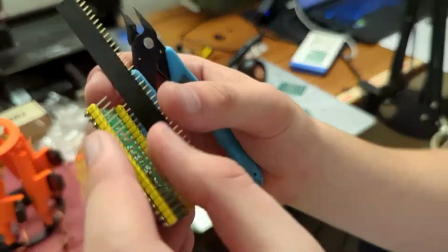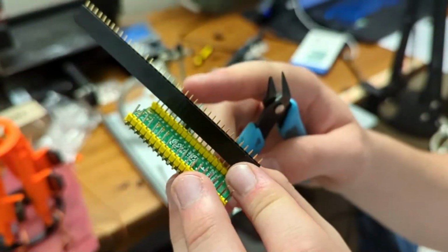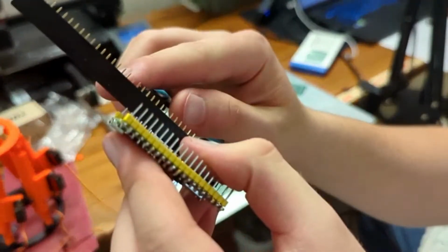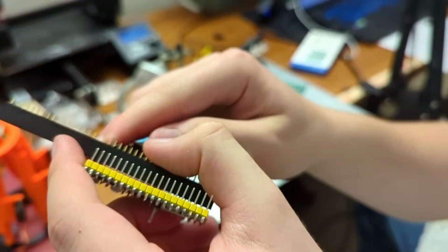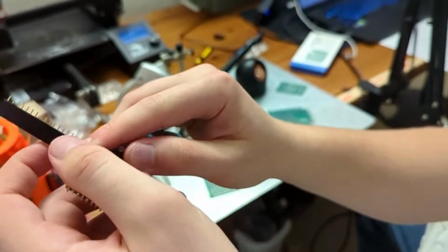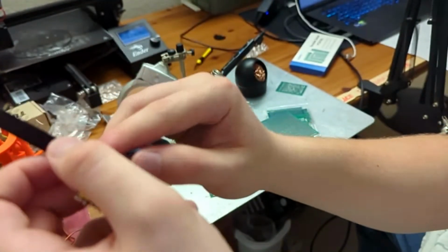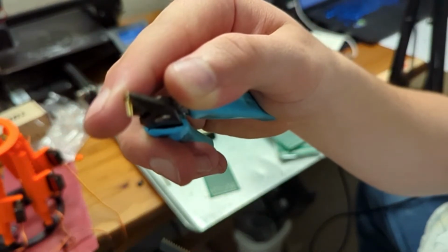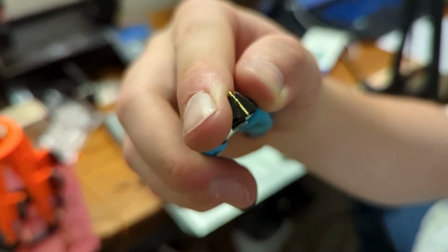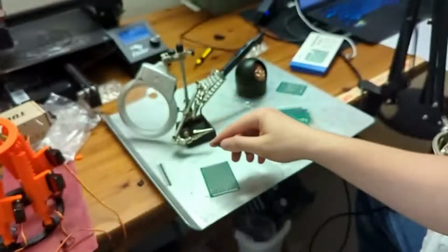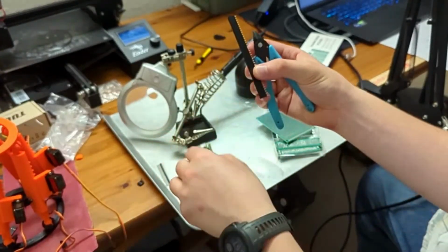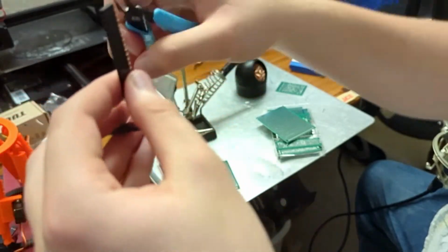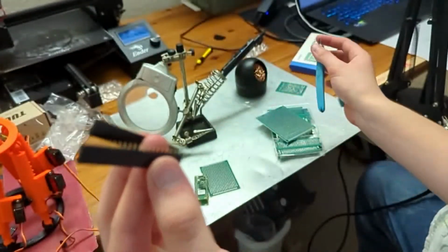For the female pin headers, what you actually have to do is you pull out one of these spines, which I will show you right here. You pull out one of the spines, just like that. See, it's just a little fork looking piece. And then on the spine you just took out, you take your flush cuts and you just basically crack the plastic, and you end up with two halves.